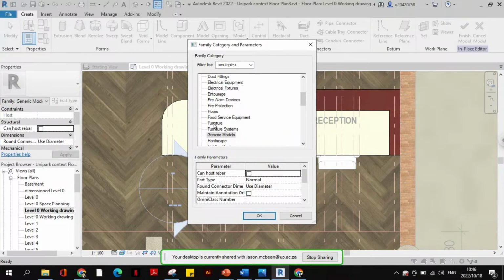So Sana, if you took this building, you took all this furniture, and you cut a section through here, you don't want to cut sections. You never cut sections through the furniture, never, because it's secondary. It's purely context. However, in your situation, this is part of your design, and when you cut a section through it, it's something that's going to be built in place from your perspective. It's something that they're going to have to manufacture. So good, you've done this correctly.